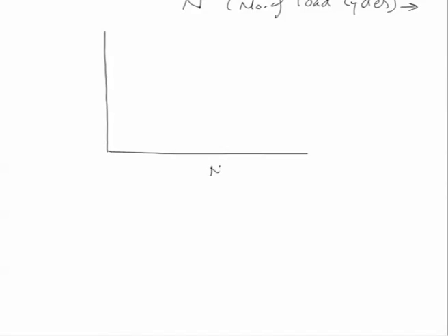If we see the same diagram for the non-ferrous metal systems, S in the y axis and N in the x axis, then for typical systems like aluminum alloys, we find a continuously decreasing trend line. So, this suggests that if we keep on decreasing the stress amplitude, the number of cycles required for failure will keep on increasing, and there is no stress limit for which the life will be infinite, or there will not be failure under the fatigue conditions.